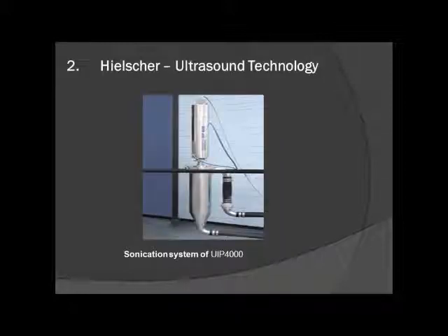The second type is the UIP 4000, with high ultrasonic output power. The UIP 4000 is used mainly for the industrial processing of liquids, such as homogenizing, dispersing, disintegrating, or deagglomerating. The powerful ultrasonic processor UIP 4000 is used when high power is needed for continuous operation. It is controlled by a microprocessor and equipped with an LCD status display as well as an interface for external control signals.